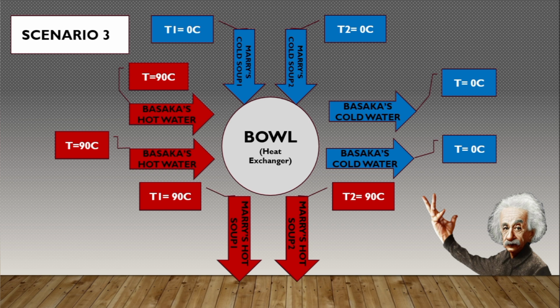So with this, we confirm that the parameter of our mass flow rate significantly affects the rate of our heat transfer. Remember, it's three things: mass flow rate, specific heat capacity, change in temperature, and majorly in heat exchanging, we deal with these two parameters: the mass flow rate and the change in temperature.